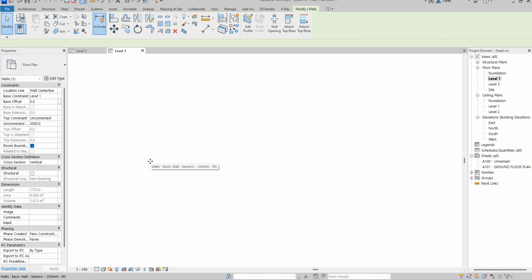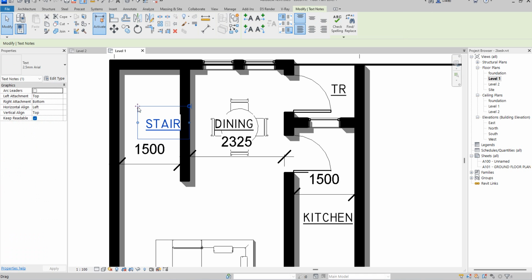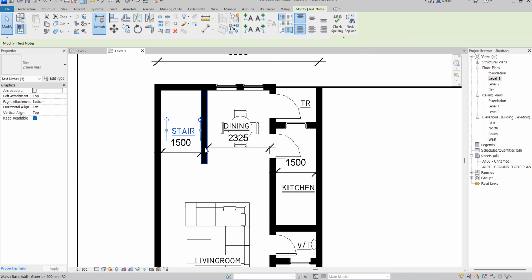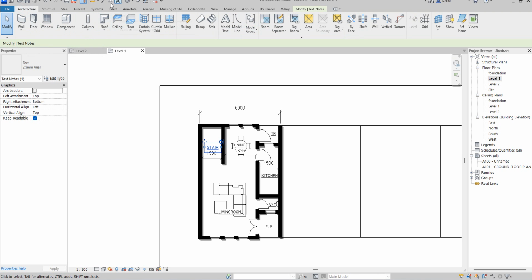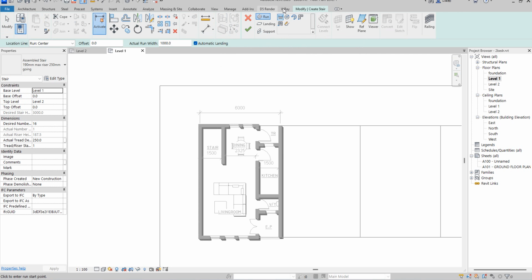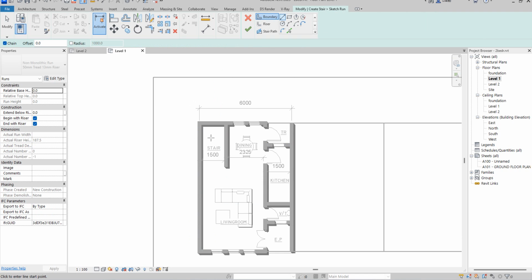I'm going to remove this particular one. So that's why I say the plan can still take another twist, but let's just move on first. The landing of the stair will determine whatever we want to do. So this stair is straightforward. You go to Architecture, then you click on Stair. On the stair, you click on Run or something like that. Just create your own sketch and do it properly, so it will give you the freedom to decide whatever is fitted to your taste.